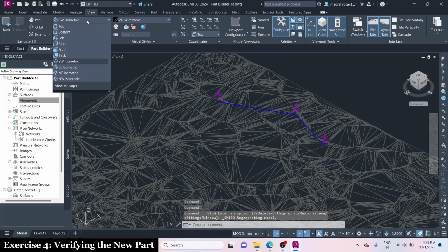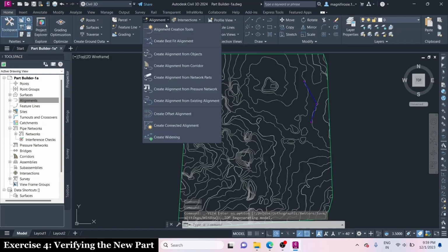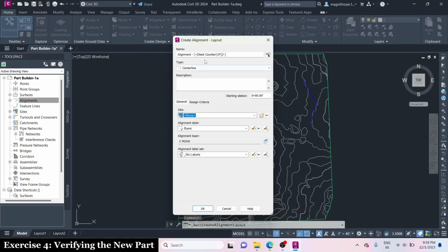Observe how your structures are displayed in Plan, 2D, views and in 3D view, Object Viewer. Make an alignment from network parts, and a corresponding profile view. Note how your structures respond to edits, adjustments, and changes of pipe inverts.